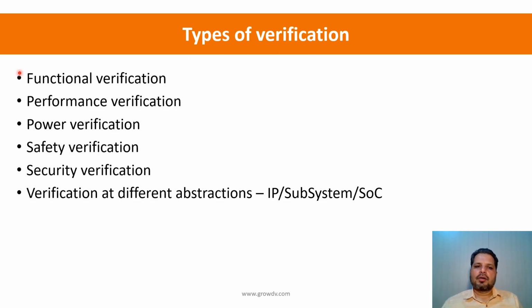So far we have talked a lot about functional verification, but there are other types of verification that are done as well. There is performance verification wherein we predominantly measure the performance metrics, which are like latency and bandwidths, and at least for the protocol type of designs, the different types of designs have different types of performance metrics, and performance is equally important as functionality. And the test bench that is created by the functional verification team is also used for the performance verification.